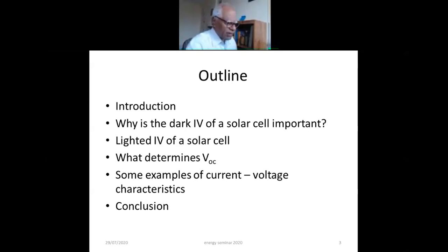Now, it looks very funny that if you're doing solar cell physics, you're going to shine light, you're interested in power. But it turns out that for understanding and for design, the dark IV of the solar cell is very important. And I'm going to show you why that is indeed so. Many people make this mistake, thinking, oh, I have the lighted IV of a cell and I don't have to worry about the dark IV, and nothing can be farther from the truth.